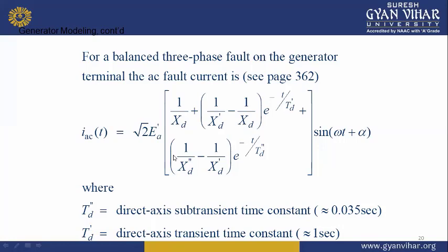Thus, during the initial part of the short circuit, the damper and the field windings have transformer currents induced in them, so that in the circuit model, the reactance XF of the field winding and XDW of the damper winding appear in parallel with XA.